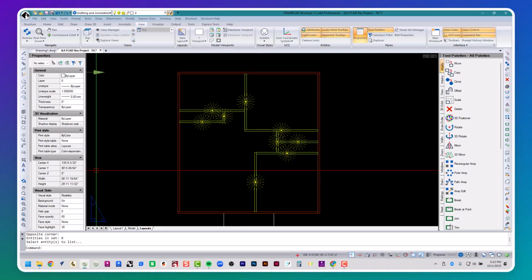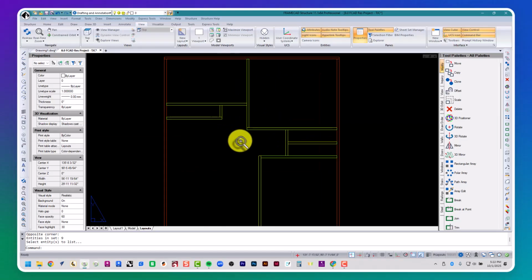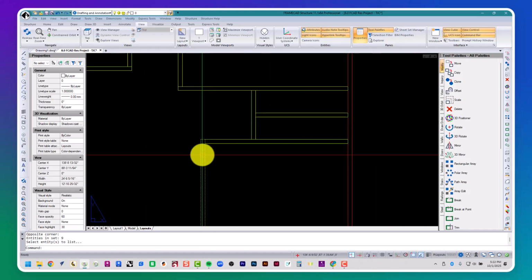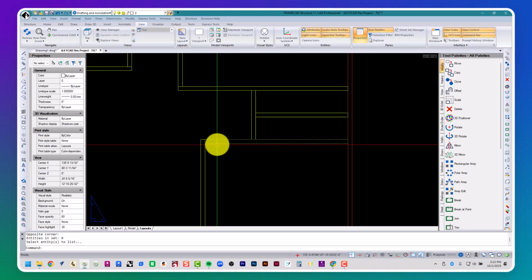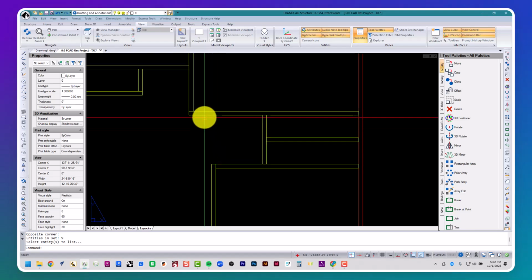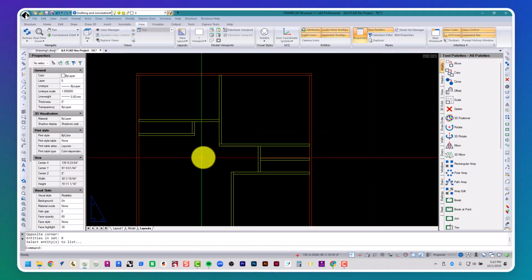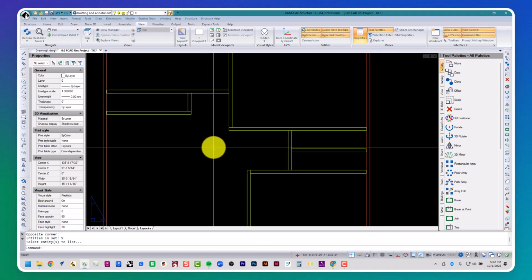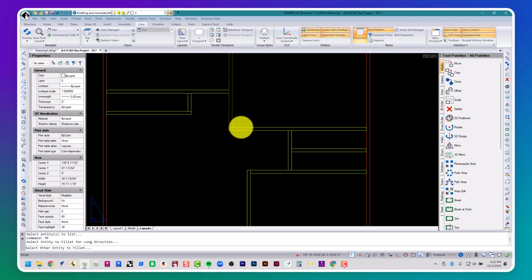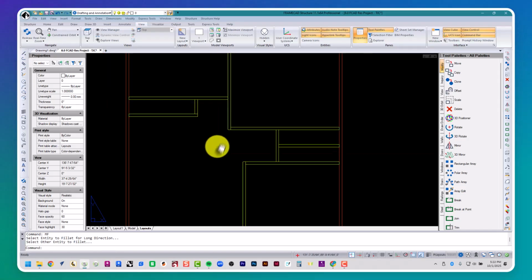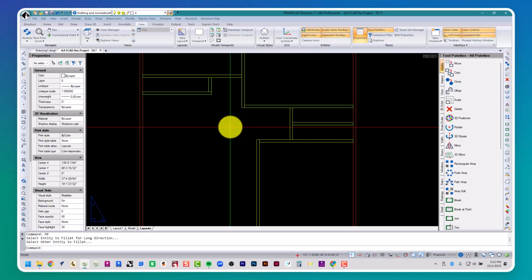We're going to tidy up some of these walls to ensure consistency. As you can see here, this wall laps over this one here. This wall laps over this one here. And generally, I just want to have consistent lapping so there's little to no confusion on the job site. For this, I can use member fillet, choose my long entity, and then my short, and these joints will change. That's the only change that I think I'll make on this one.